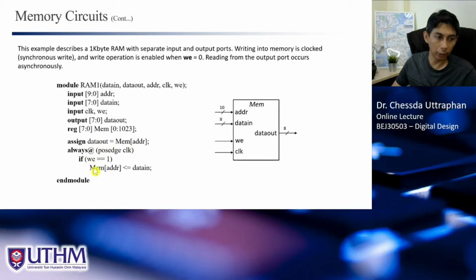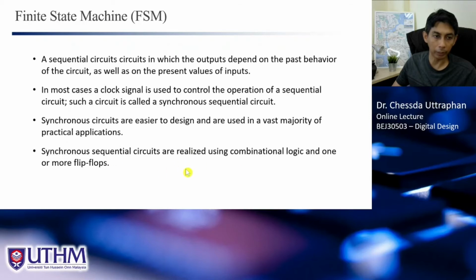And if we want to write, to write we have one signal here. We call it the write enable signal, WE. If write enable equals 1, then we can write the data into the memory. If we write like this, it means that our read can always read anytime, what we call the asynchronous read, because this will not depend on the clock, so we can read anytime. But the write depends on the clock. We can only write at the positive clock edge, and also we need to wait for this signal to be activated, then we can write to the memory.